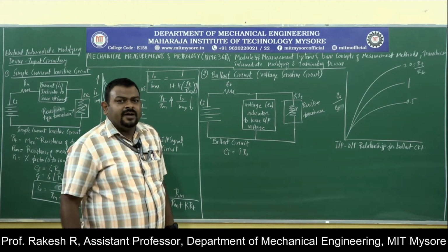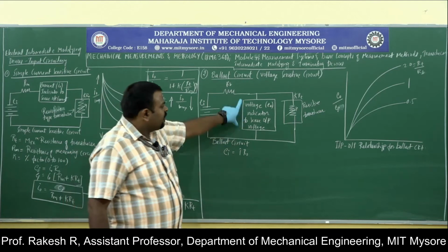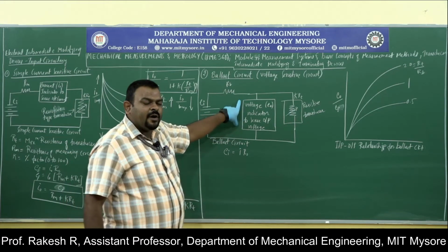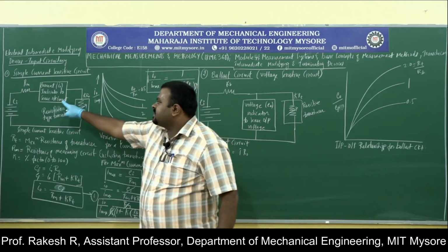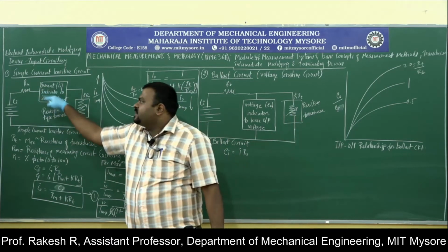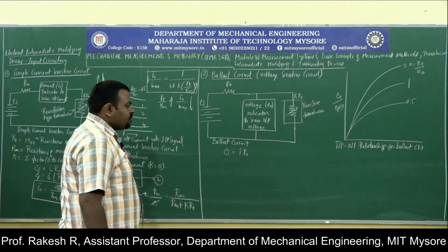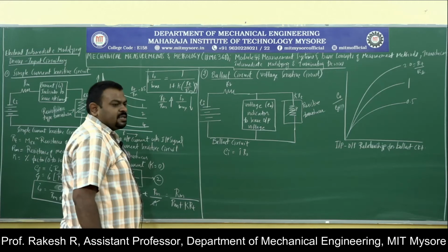And remember, whenever you are calculating the voltage, you have to connect in parallel. When you are measuring a current, that should be in series. These two are very important things here. You need to remember this. If you miss this, you will miss the marks.